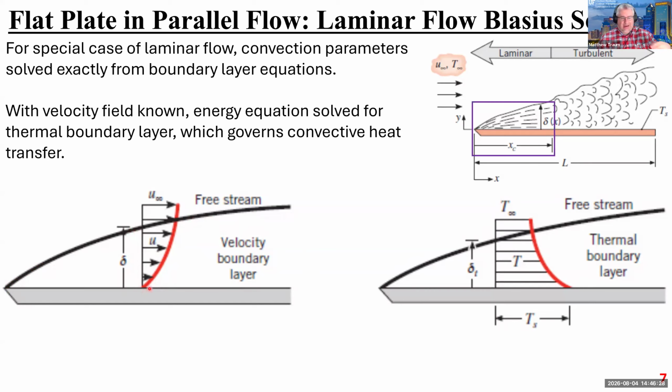Well, the boundary layer is kind of this arbitrarily decided barrier, if you will, between where the plate has influence on the velocity field and where the plate does not have influence on the velocity field for flow that's headed over the plate. So it's by convention agreed upon that the boundary layer is the spot where the velocity reaches 99% of the free stream velocity. That's just an arbitrary engineering decision.